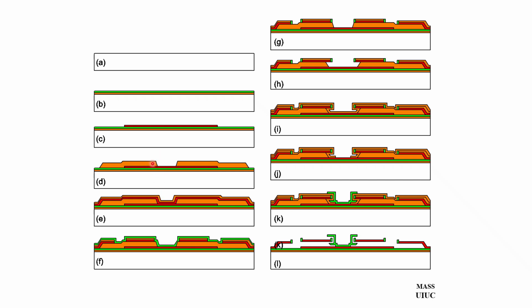This is then patterned and then coated again with the second polysilicon structure. The polysilicon is patterned and then covered conformally with a silicon nitride layer. Now, the silicon nitride layer can be patterned and etched using plasma etching. If you control your plasma etching process well, it will become anisotropic, namely the surfaces that are facing the electrode would receive a faster etch than the silicon nitride on the edges.